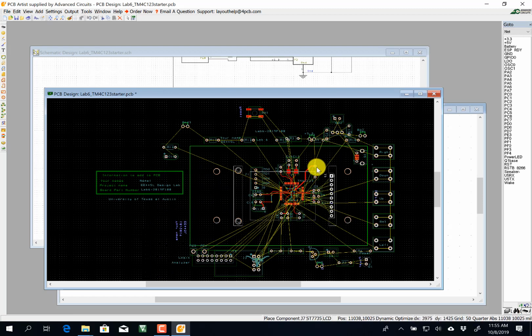You can see I'm aligning the back two holes with the drill holes. Now the colors: this blue is silkscreen on the other side of the board. This cyan is silkscreen on the top side of the board. Then I'm going to go one by one, asking which side of the board things are on. This is my reset switch.